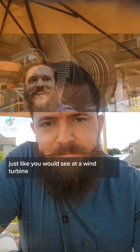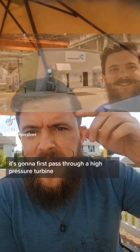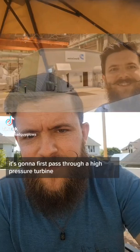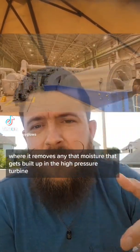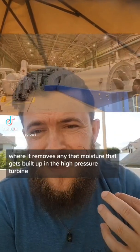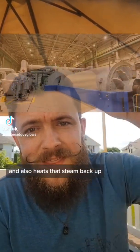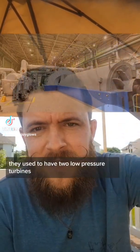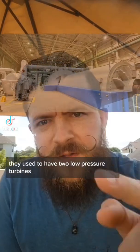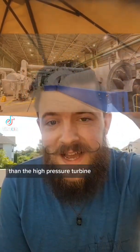After the steam comes out of the steam generator, it's going to first pass through a high pressure turbine. Then it's going to go through what's called a moisture separator reheater, where it removes any of that moisture that gets built up in the high pressure turbine and also heats that steam back up. Then it's going to go into your low pressure turbines. At the Kewaunee plant, they used to have 2 low pressure turbines. Those low pressure turbines are always going to be a lot bigger than the high pressure turbine.